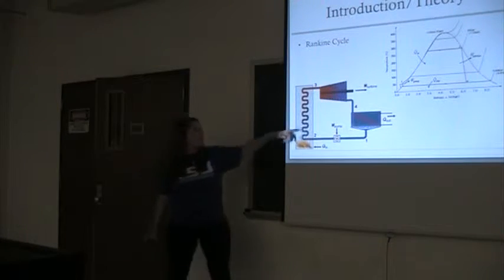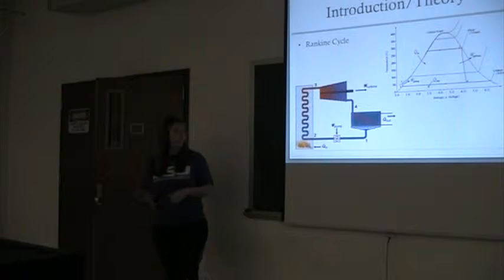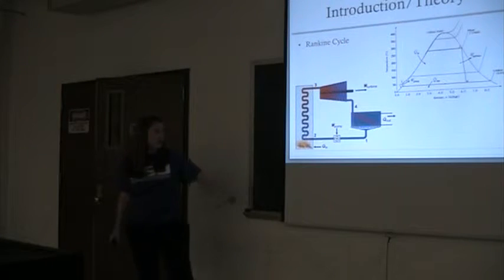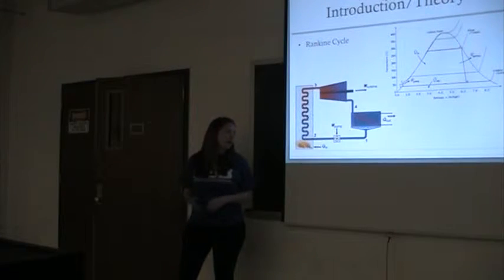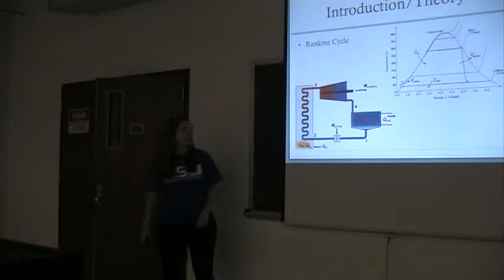The working fluid will rotate a shaft which is connected to a generator which outputs the power. And then the fluid is cycled back to the condenser, which obviously condenses the fluid by circulating cooling water. Then it goes back into the pump as a saturated liquid.